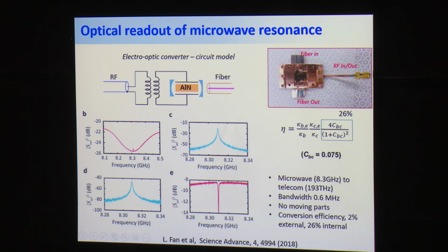It's more interesting actually to look at the reflection from its ports. If you look at the RF port reflection, it's very simple, right? Just a resonance. What's more interesting is to look at the optical port reflection. Here you just see the optical mode, which has a line width of about 200 megahertz. And at the bottom of the optical reflection, that mode, you see this superconducting resonance. And that's due to your infinity resonator resonance. So you actually optically drive that resonance and optically read out that resonance.